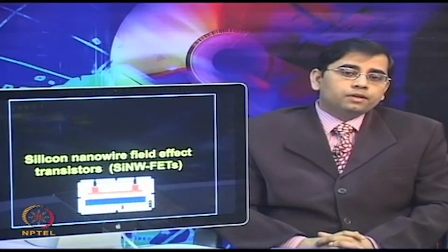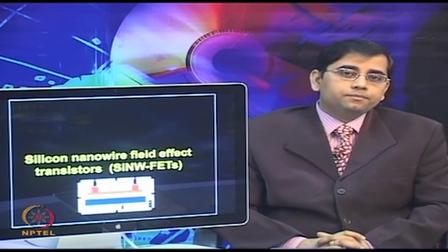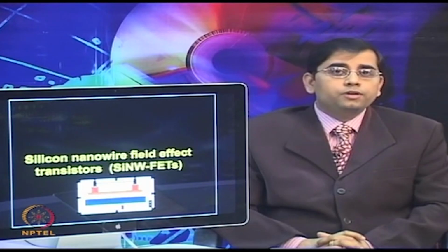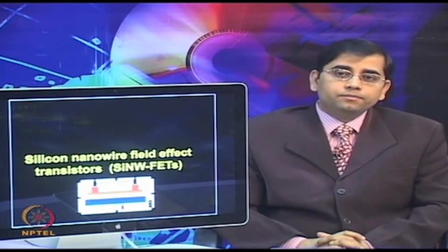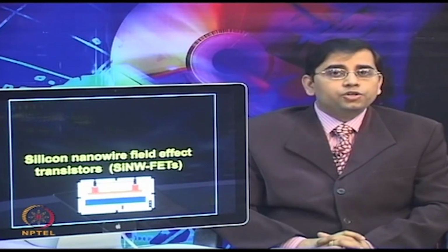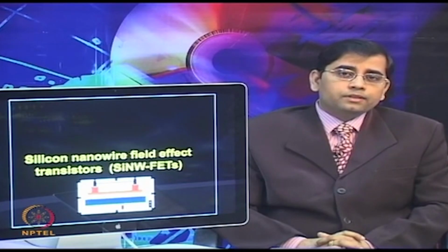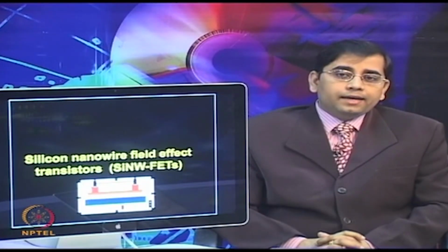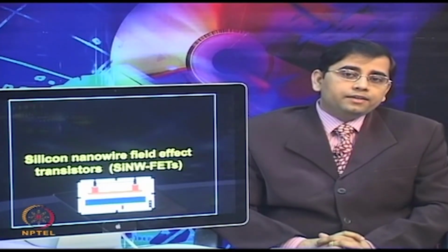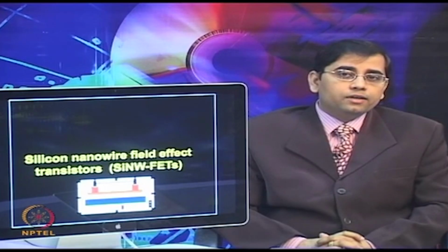Let us now talk about silicon nanowire field effect transistors or SiNW FETs. The planar field effect transistors modified with molecular receptors for the analyte of interest can monitor the binding of charged species through the accumulation of carriers on the surface of the transistor. Although this transistor translates directly into readily measurable changes in conductance or related electrical properties, their physical parameters pose constraints for sensor fabrication.